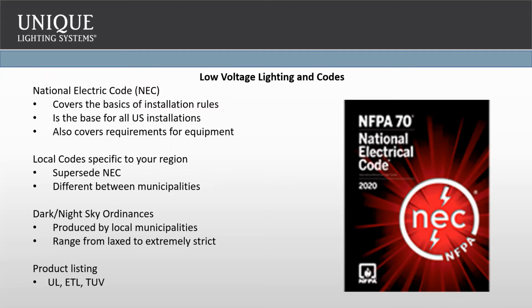There are several municipalities out there that do have local codes, and just like anything else that we do in design, the local codes will supersede the NEC, but the NEC is there if there's nothing that exists. My experience has been there are very, very few municipalities that have local codes pertaining to low voltage. And if they do, they probably haven't been updated in a while, and it gets a little tough.